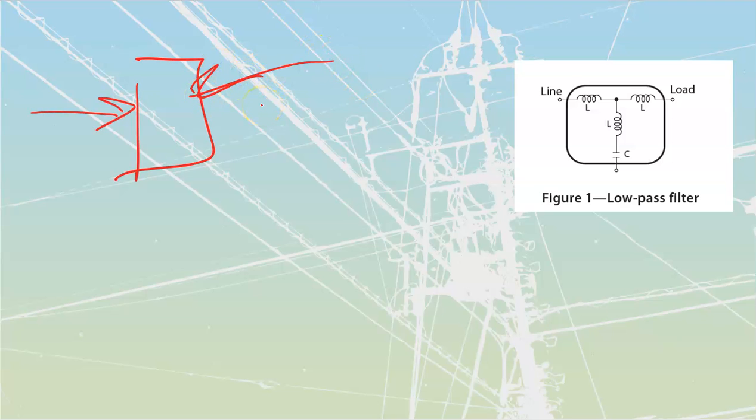Transient voltage surge suppression is going to filter spikes that come in from the outside generally. We don't have a lot of spikes we generate ourselves. Noise filters are going to filter stuff that we have inside so it doesn't go out and cause problems anywhere else. Once again, these are going to have to be sized on a case-by-case basis, and you have to know a lot about that installation: tracking down, logging, and writing down all the cable lengths, cable types, even cable insulation is critical because of its dielectric constants, all this other stuff.